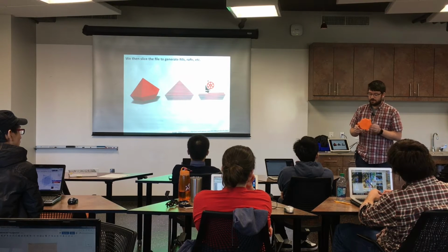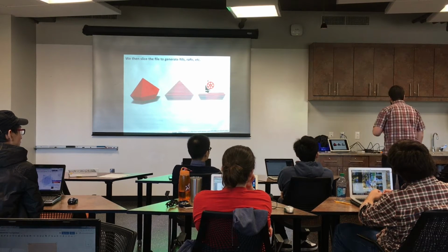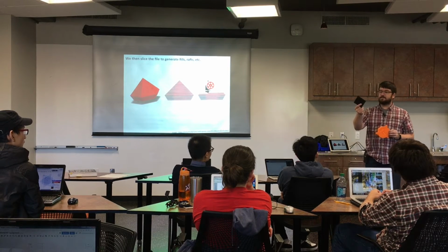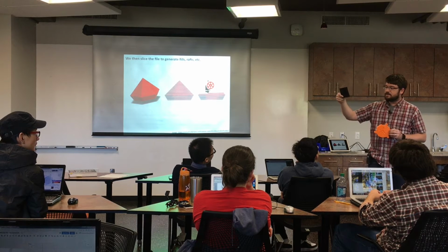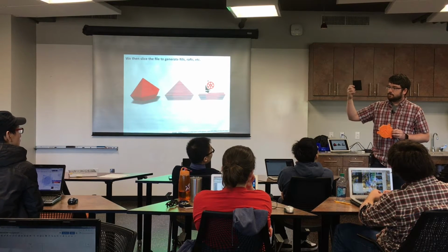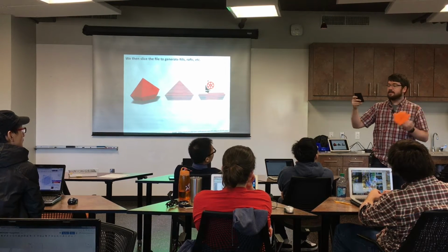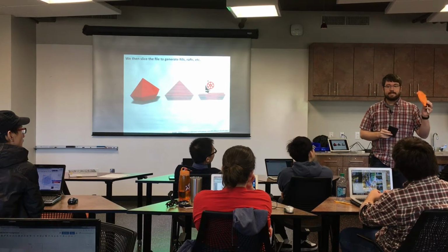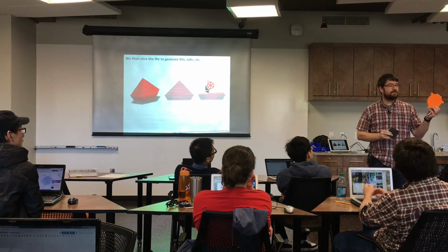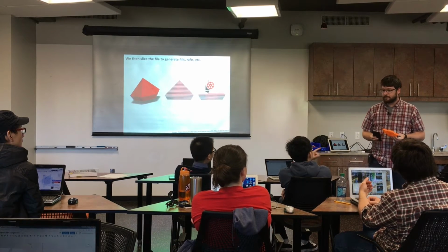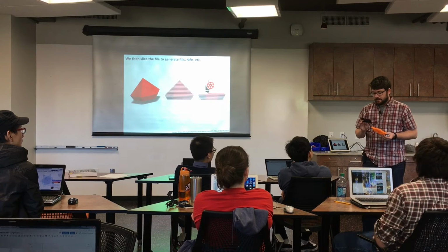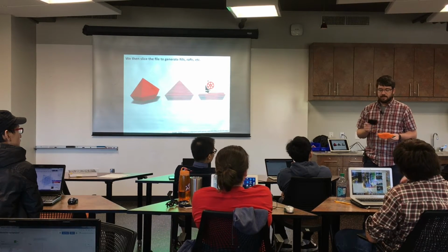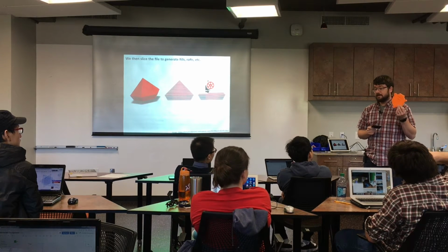But there's a lot of parameters. Like you can change how much infill there is. It's probably really hard to see, but this part has a really dense infill. The network is really, really close compared to this. I did that because this part needed to be sort of strong, and this didn't. This was just to see if it would fit where I thought it needed to. How long will it take to print this solid part? So it's not quite solid, but it's almost solid. So this would probably take a couple hours. And this would probably take a couple hours as well, but it's a lot bigger.